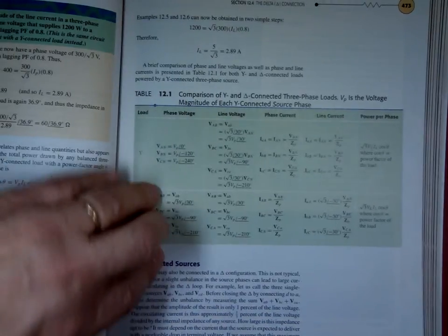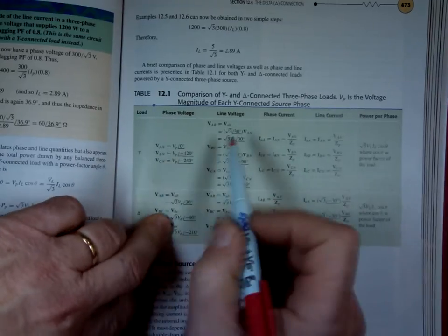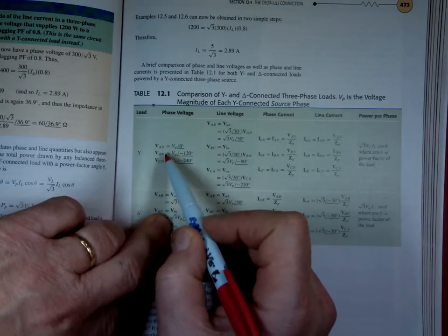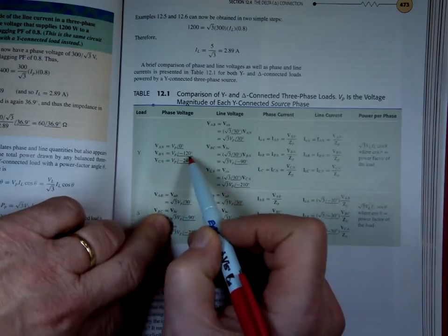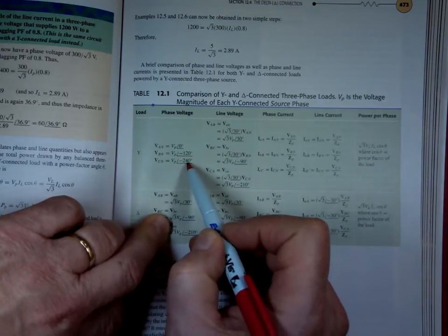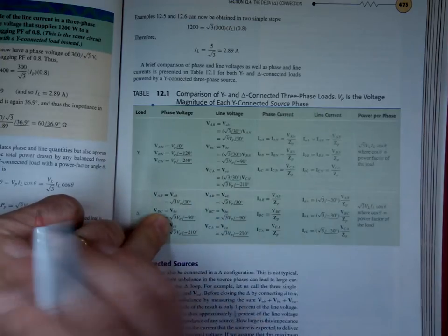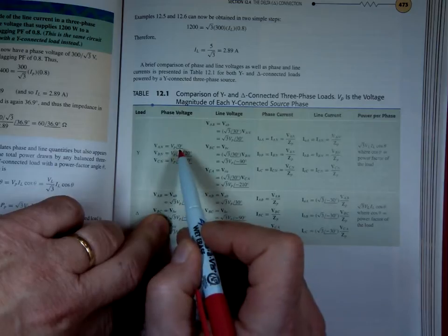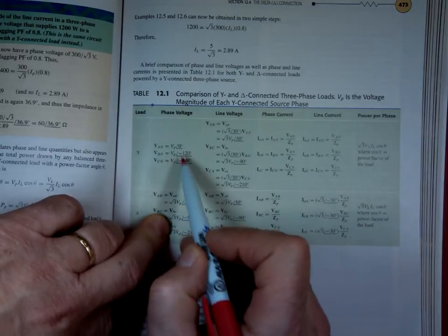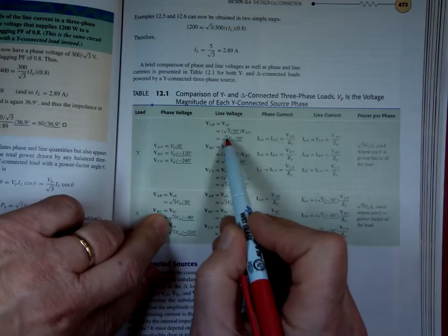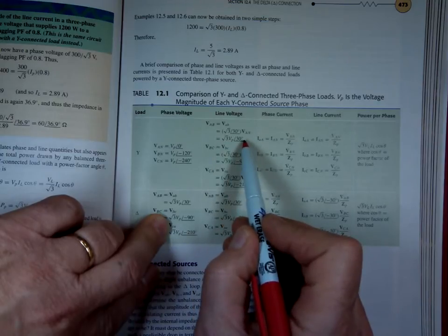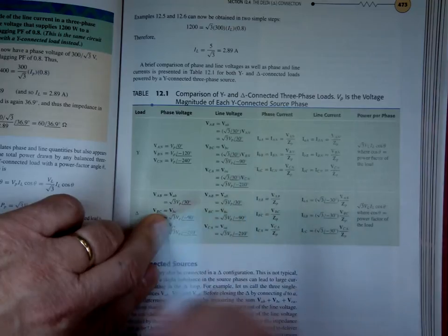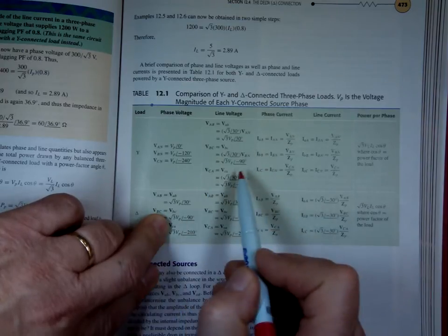But it says if you have a Y load, you know VAN, that's the load here, capital A, see that, capital A? VAN, then VBN is going to be 120 off that number, and this is 120 off this one. That's where the 240. What is AB is going to be? Obviously, they're using here positive sequence. See the positive sequence? So we multiply by the square root 3 and add 30 degrees. VBC, again, subtract 120 from that number, which is negative 90. VCA, subtract another 120 from this, and that's where the 210.